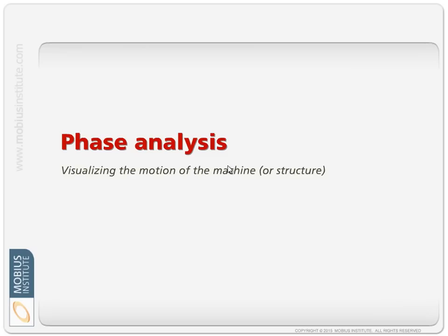All that force translates into movement of the bearing. It moves up and down and side to side with, for example, unbalance. But it moves differently if it's misaligned, and it moves differently if there's a cocked bearing and other sorts of faults. So that's what phase analysis does. Phase analysis lets us step back and think about what's actually happening to the machine as a whole. How is the vibration, or how's the fault condition, causing the machine to move? And that tells us a lot about the fault.